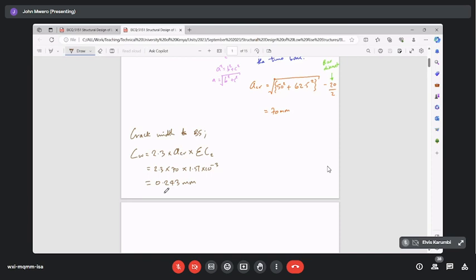If our concern is the durability of the structure, for example, when we design bridge structures or box culverts, the standard gives guidance to say that for bridge structures, water retaining structures, culverts, and basically road drainage structures, because of the continuous passage of water, the crack size must not exceed 0.25 millimeters. That is why this calculation was stopped here, because this wall is a culvert wall, and the crack size that was calculated was found to be lower than the maximum allowable, which according to BS, if I can remember properly, is 0.25.